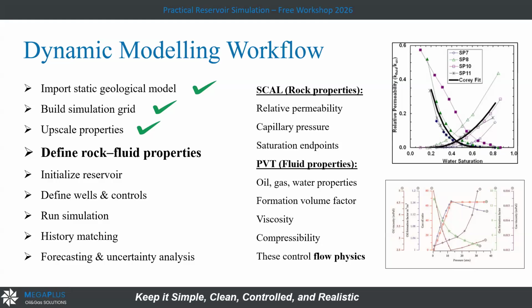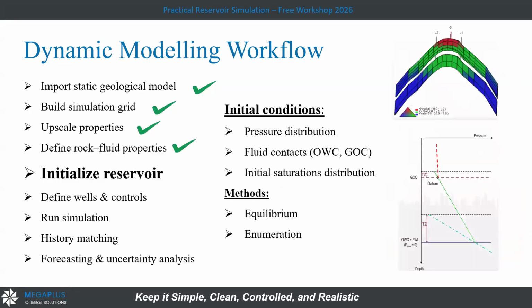Saturations, so relative permeability and the capillary pressure, and in fluid, of course, it will change with pressure in the form of viscosity and density and formation volume factor and all of that. All of these tables I have to insert in the model. And then we will go through the milestone of reservoir simulation called initialization. What is the initialization? Simply, and we will go into details after this slide.